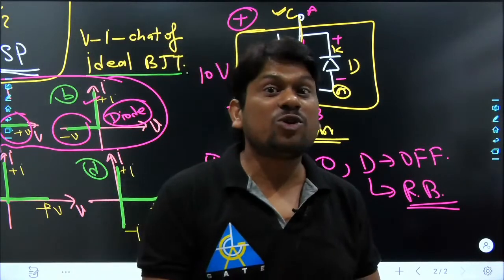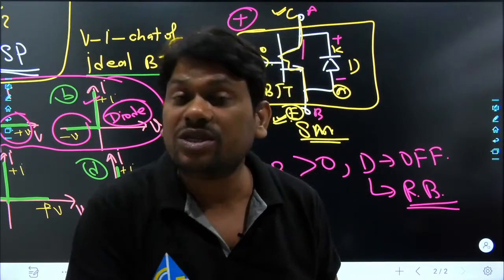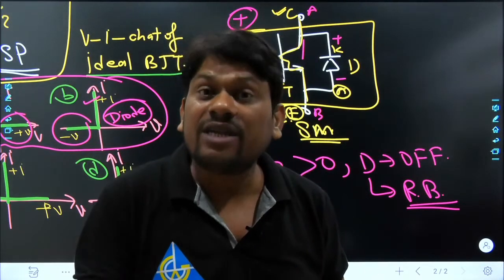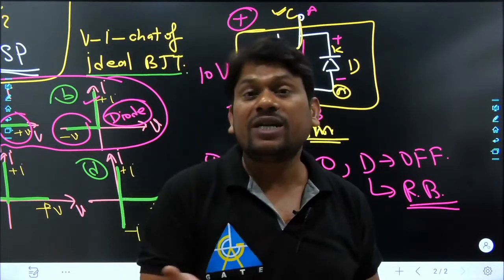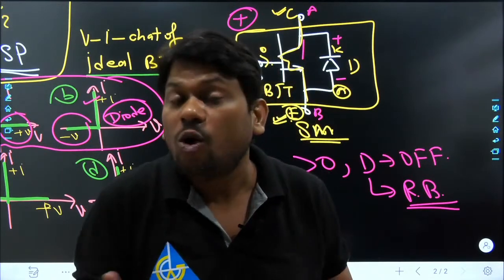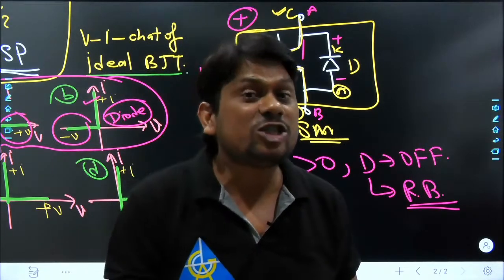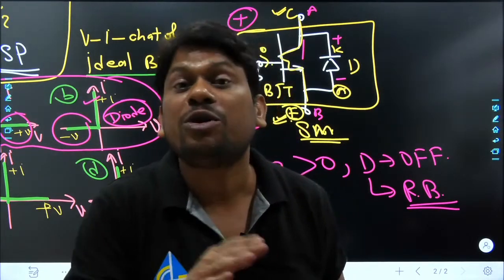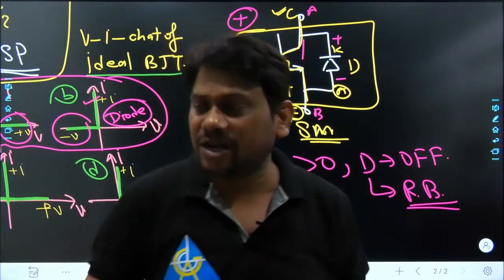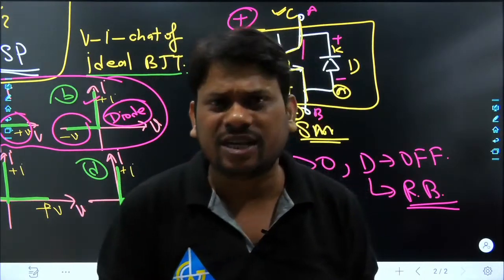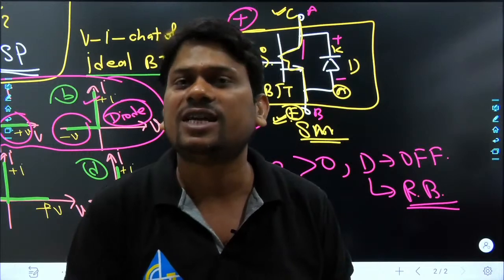And for the conduction, all the junctions, that means 2 junctions present in the general BJT, and 3 junctions present in the power BJT, must be forward biased for the conduction of BJT. And that job we cannot complete without base current. So my dear friend, if you are not applying base current to the BJT, nobody can turn on this BJT anyhow.